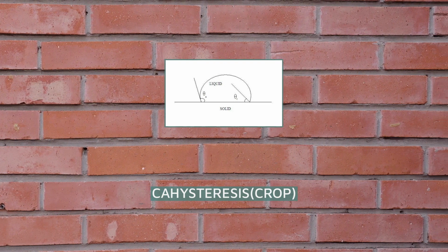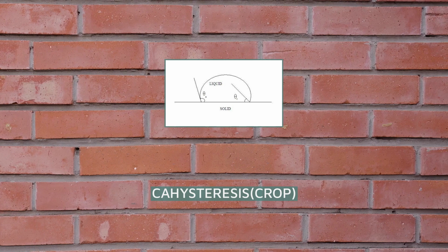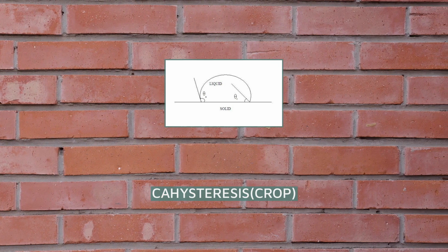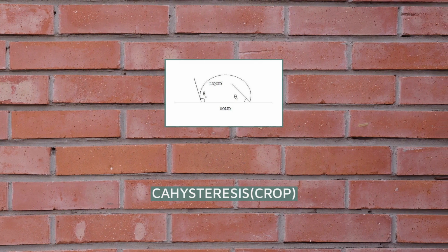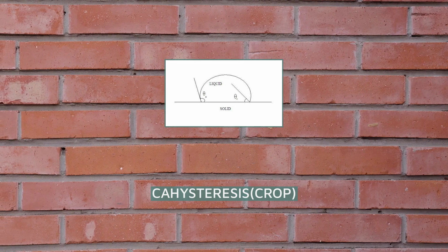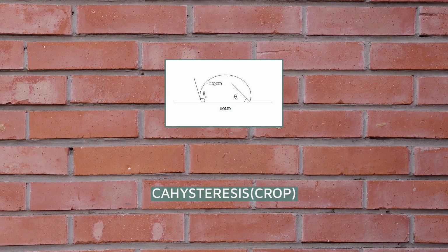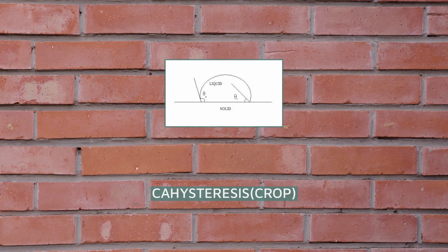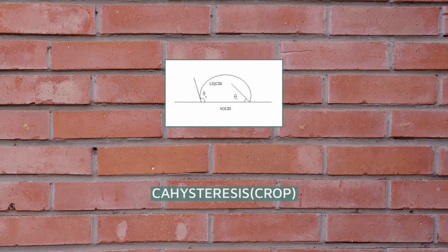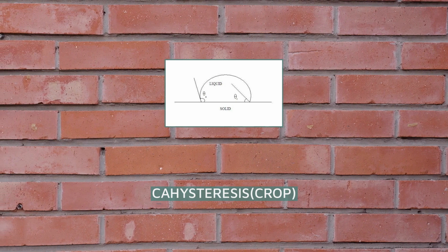Contact angle hysteresis occurs because many different thermodynamically stable contact angles are found on a non-ideal solid. These varying thermodynamically stable contact angles are known as metastable states. Such motion of a phase boundary involving advancing and receding contact angles is known as dynamic wetting. The difference between dynamic and static wetting angles is proportional to the capillary number, Ca.